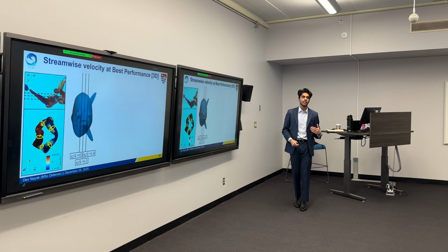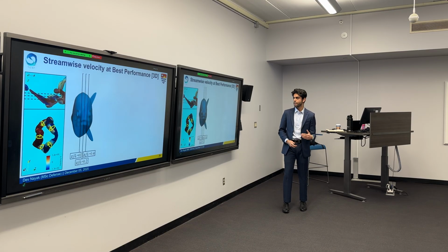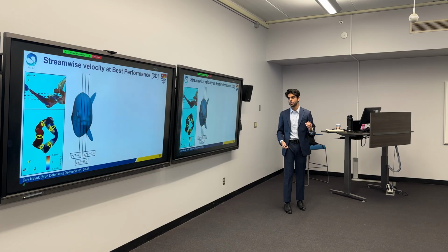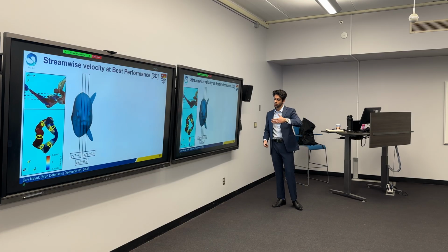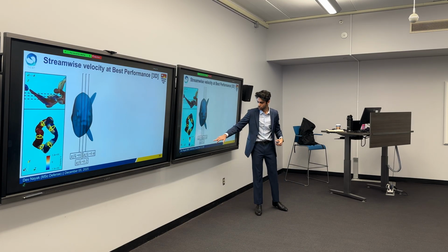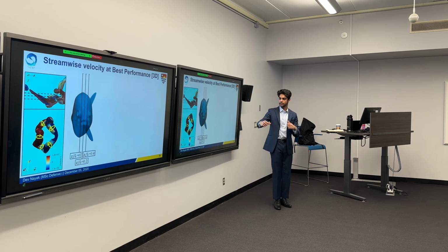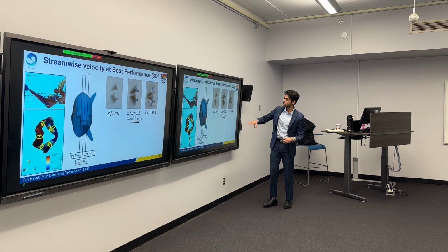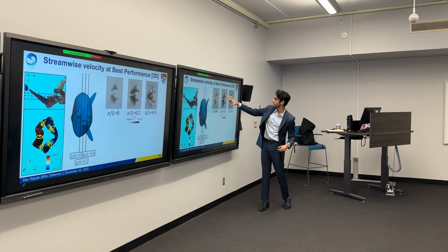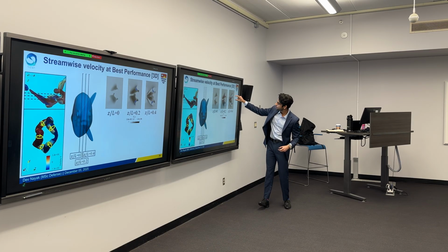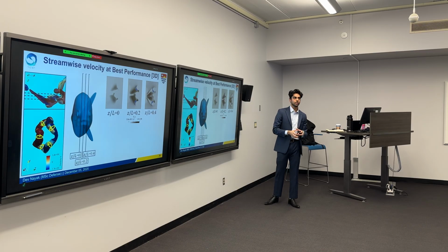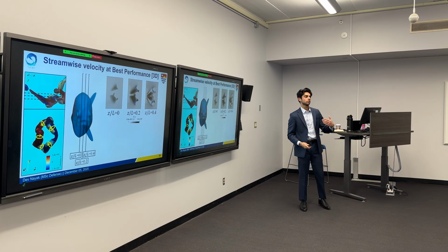And we can observe that by plotting the instantaneous velocity diagram when this vortex is shed. So we can take the sectional view at 0, 0.2, and 0.4 in the z direction. And when we look closely, around the trajectory, at the frame of the vortex, it creates a very narrow jet-like effect around that ring. That is the one that contributes towards thrust.